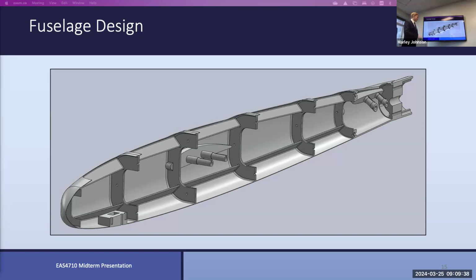That's definitely a really good suggestion. But obviously there are other considerations. You've got to physically be able to get your hands or a tool in there to fasten something. The main reason we didn't do this was for ease of assembly. Accessing something down here might be tough, because you're coming in from the top. We also did determine that these are relatively stiff enough that with fastening washers, it is stiff enough to spread out that force. Once we test some more, we could definitely try something like that in the fastening location. That probably gives you a better, thinner structure for the two different bulkheads.